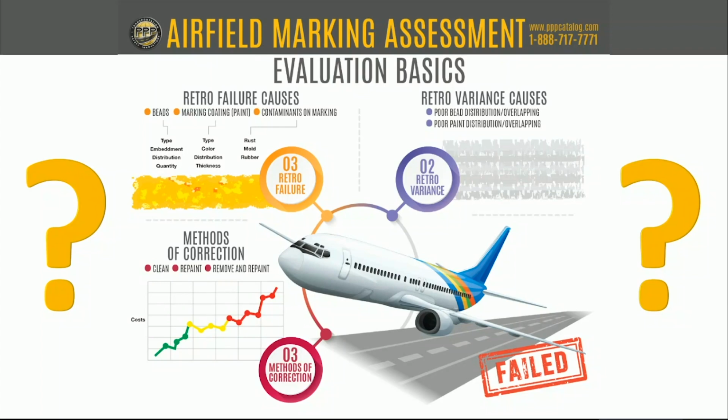It's something that we use on the roadways because it lasts so long, and also because its retroreflectivity rejuvenates, since it's got intermixed beads instead of just beads on top like paint does. So you'll get longer retroreflectivity, and longer wear as well. But again, there are limitations as to where you can use this on the airfield. In the roadway industry, I've seen 10-year-old thermoplastic and it did okay, but realistically, 3 to 5 years.